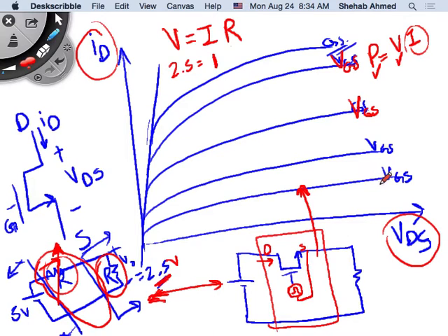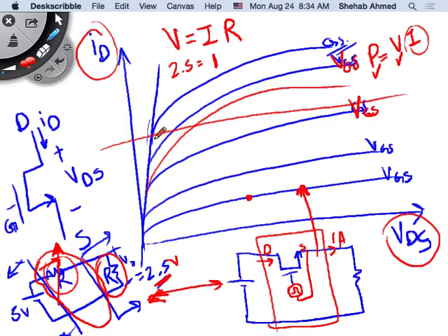So if you provide different gate-to-source voltages, your operating points change. Let's say you're pushing a current of 1 amp, then there's a specific operating current here, right? If your drain current needs to be 1 amp, then you have a specific current that you're operating at. So these curves here will intersect this 1 amp value of drain current at several points. They can intersect here, here, here, maybe another one will intersect here, or whatever, right? So there will be several operating points that you can operate at, and they will be based on different gate-to-source voltages, right?